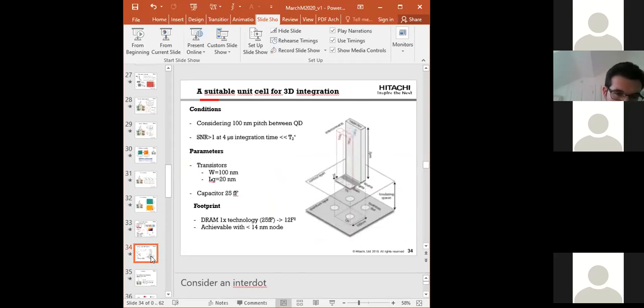What we did is to just check what is available in terms of the modern technology. Of course, we are talking about much smaller capacitors because as soon as you go large in capacitance, the footprint becomes also unmanageable. Yeah. But these vertical capacitors are already manufactured. They use this type of structures for DRAM in this particular technology called DRAM 1X. And you can have that very small footprint of 100 by 20 nanometers. Yeah, maybe 100 by 40 nanometers.